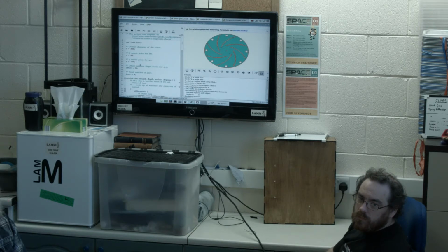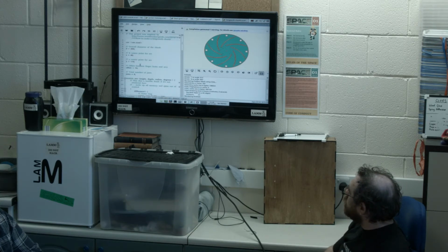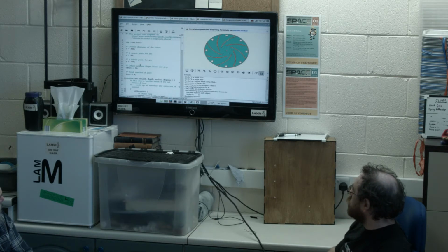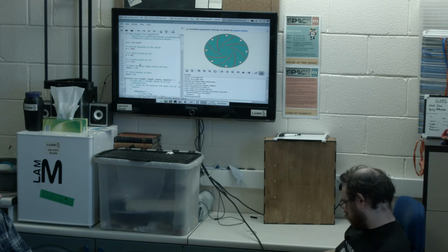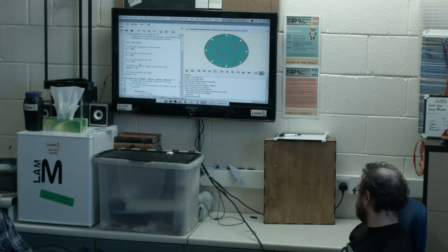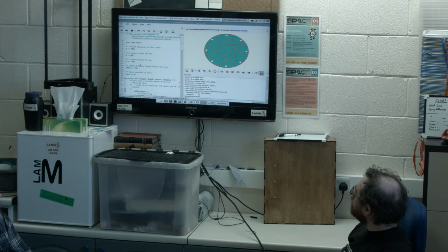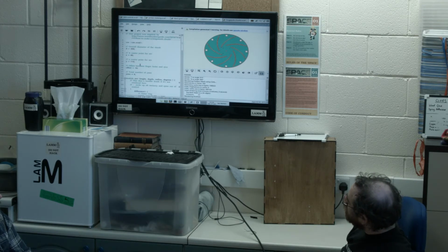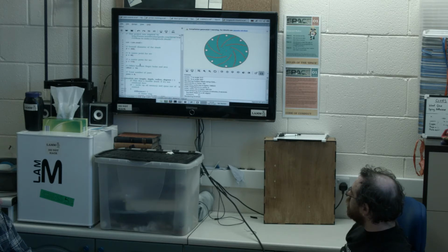Like if for some reason you're stuck in a version where you only have radius, you put a variable saying circle R, and then a variable underneath which is circle R times 2. Then when you have your whole thing and you say, oh bugger, this needs a millimeter in or out, you just edit that variable and press F5, boom, you have a preview. That's one of the things that I'm missing in FreeCAD.